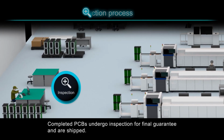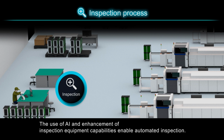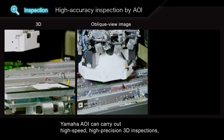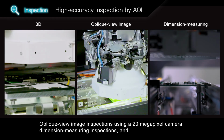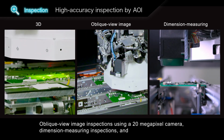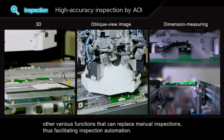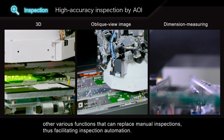Completed PCBs undergo inspection for final guarantee and are shipped. The use of AI and enhancement of inspection equipment capabilities enable automated inspection. Yamaha AOI can carry out high-speed, high-precision 3D inspections, oblique view image inspections using a 20-megapixel camera, dimension measuring inspections, and other various functions that can replace manual inspections, thus facilitating inspection automation.